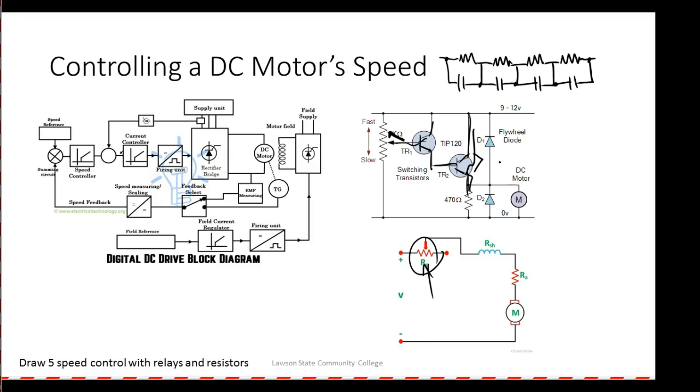So what they did is they took an AC signal like this, and we switched it up to both sides. Now the motor is going to average this out. Anybody know the formula? It's 2V peak over pi.